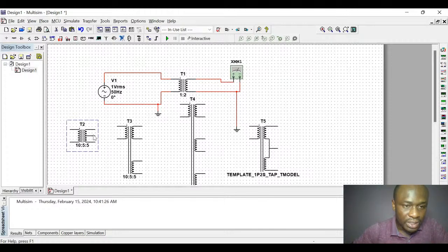this way. It has different levels of secondary coils, maybe the first coil will be 10 turns, the second one 15, the third one 20, the following one 25, as the case may be. So if the voltage level is 120, and for it to correct to 220, it has to switch to secondary coil 3.